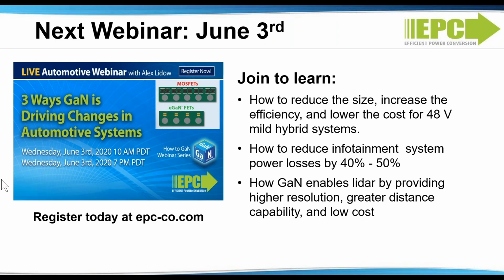Do you foresee GaN to be self-protecting in breakdown anytime soon? So our GaN devices have a 20% over voltage rating on them. For example, a 100 volt device can be used at 120 volts for short periods of time. That's because we do not have an avalanche rating.